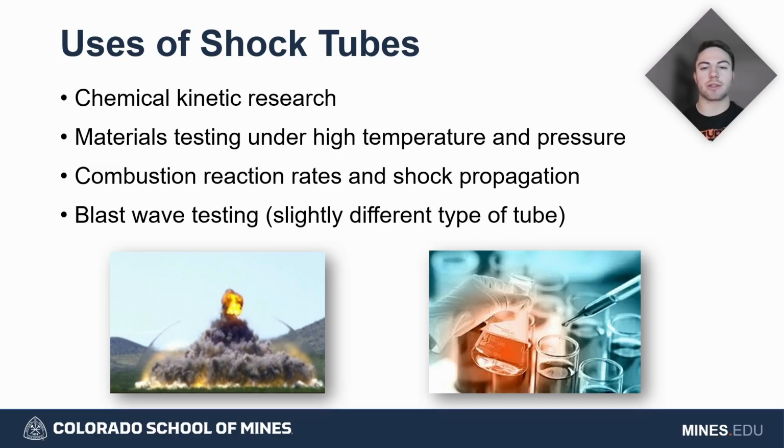We'll quickly go back into shock tubes here and what they can be used for, because they're very important, and this is one reason I built this model, to make a mini shock tube as well as show some math behind it. So in chemical kinetic research, you can figure out your K factors and a lot of other data from different reactions by blowing them up and figuring out the pressure and the speed difference of the flame as it goes through the tube and then breaks through into your shock chamber.